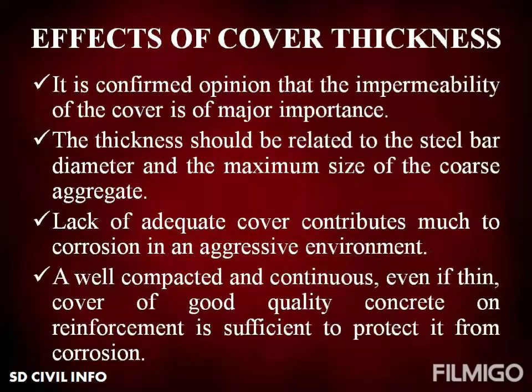It is a confirmed opinion that the impermeability of the cover is of major importance, and the thickness of the cover should be related to the diameter of the steel bar and the maximum size of the coarse aggregate, and the lack of adequate cover contributes much to corrosion in an aggressive environment. Finally, a well compacted and continuous, even if thin, cover of good quality concrete on reinforcement is sufficient to protect it from corrosion.